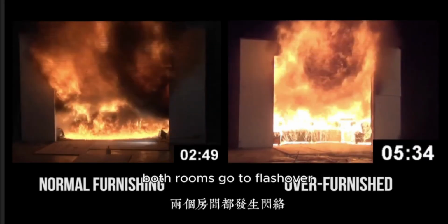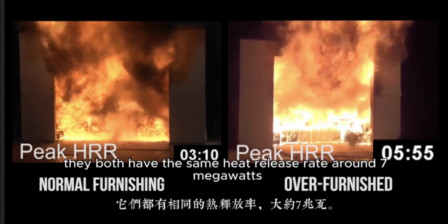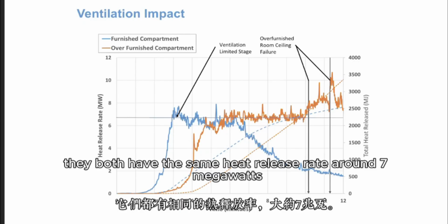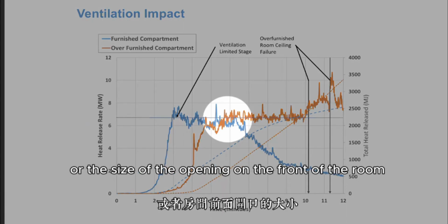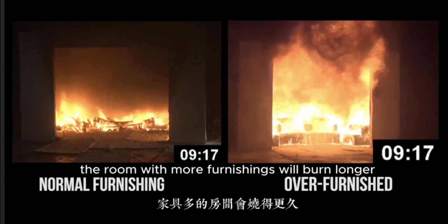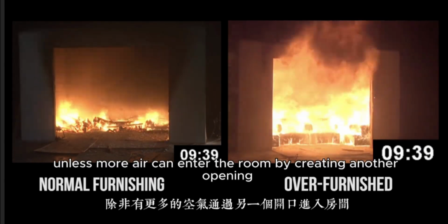Both rooms go to flashover, and even though one has significantly more furnishings, they both have the same heat release rate, around 7 megawatts, because the size of the fire is limited by the amount of ventilation, or the size of the opening on the front of the room. The room with more furnishings will burn longer, but it won't release more energy unless more air can enter the room by creating another opening.